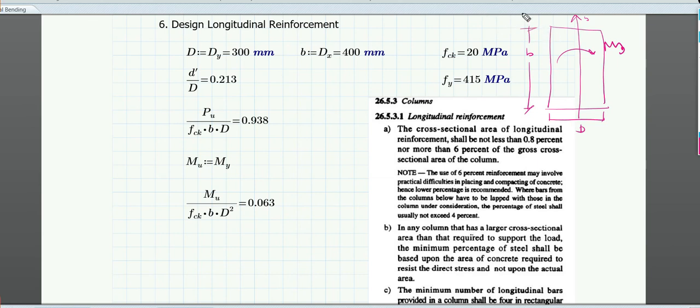As per that particular graph, we can see that it's a rectangle which is 300 by 400, so the reinforcements are provided on the two sides only, because to take care of the moment, the moment will impart some tension, and that tension will be taken by the reinforcement. As the moment is acting in this direction, reinforcements are provided along this side. If the moment were about the x direction, then the reinforcement would be on the other two sides, and if it's a biaxial moment, Mx and My, then the reinforcement will be equally distributed all along the sides.